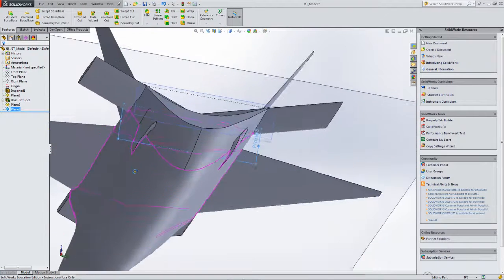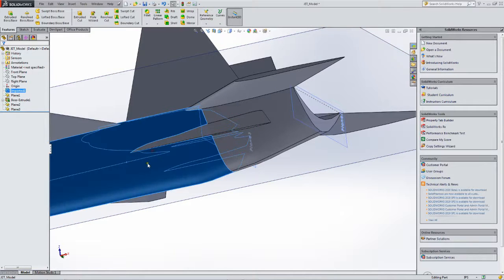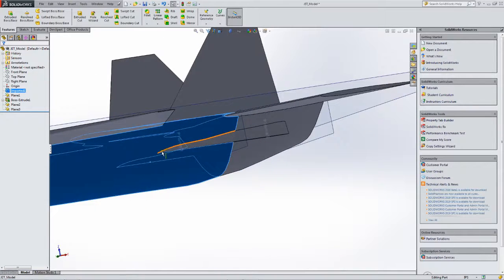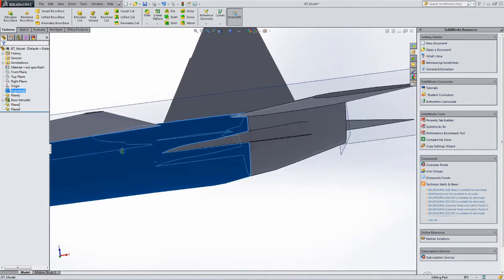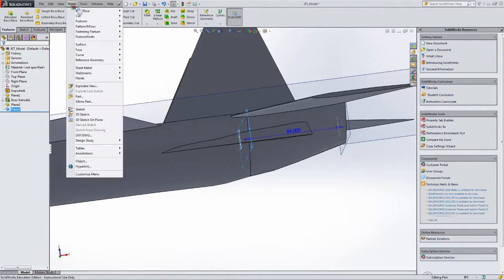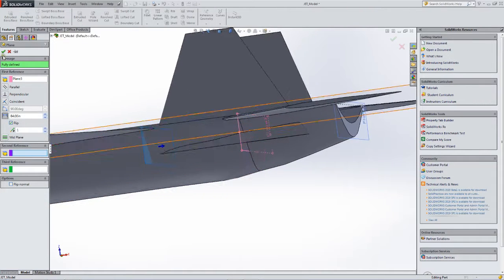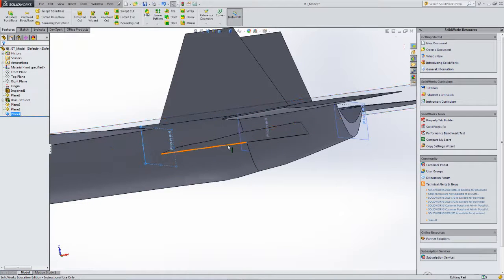And now the last one is a little trickier. We're going to just put it right here ahead of the farthest forward point where this thing sticks out. And so we'll go another about the same distance. So that's convenient. We highlight, now I clicked it over here, I could also click it here in the drawing. We highlight plane 3, insert reference geometry plane, and we want to flip, and I think that'll be far enough. Okay, so that's good. Alright, so there's our 3 planes.